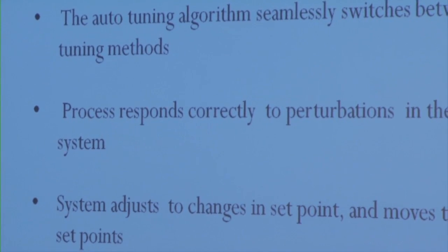So how significant is what we have done? The fact that we were able to seamlessly switch from Ziegler-Nichols to Tyreus-Luyben, and that the process was able to maintain its stable points even when there were perturbations like the opening of the valve or the changing of the set point, is really important, especially in industrial settings where processes have to be maintained at a set level. Also, by simulating this bioreactor, we can apply the same principle to other processes, both biological and chemical. Now I'll hand it over to Steve for the conclusions.